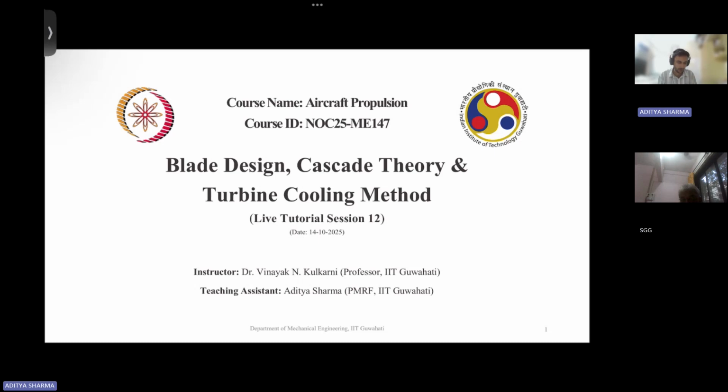From here, if we place T naught 3 on the left hand side and all other terms on the right hand side, T naught 1 is given to us, and T naught 3 dash we just calculated from the pressure ratio.